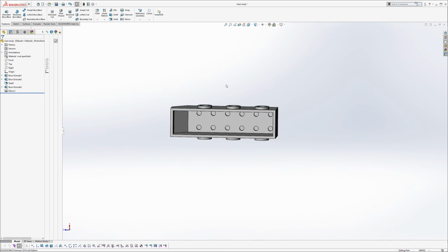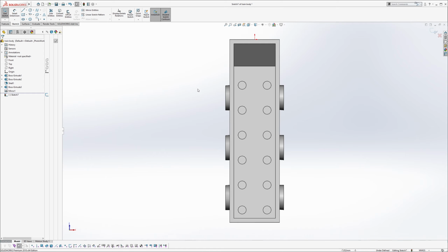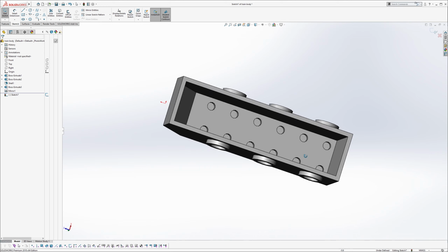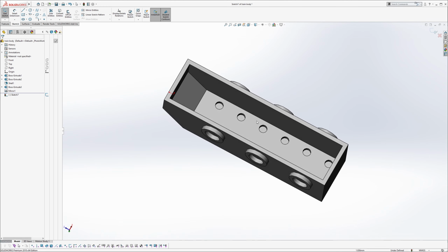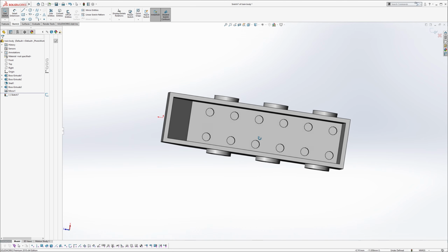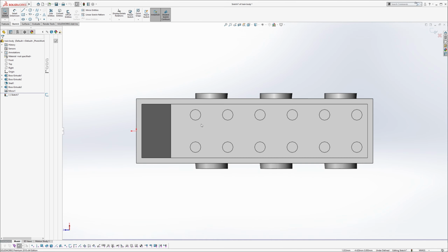One way to do that is we're going to select this face here and hit, I can also use this normal too, and then hit over to sketch. Now I'm sketching on this view, but I kind of want to rotate it and view it this way. So I'm going to hold my scroll wheel down and then move to the desired location. And then I'm going to hit the space bar and select this face. Now I'm in this horizontal view.